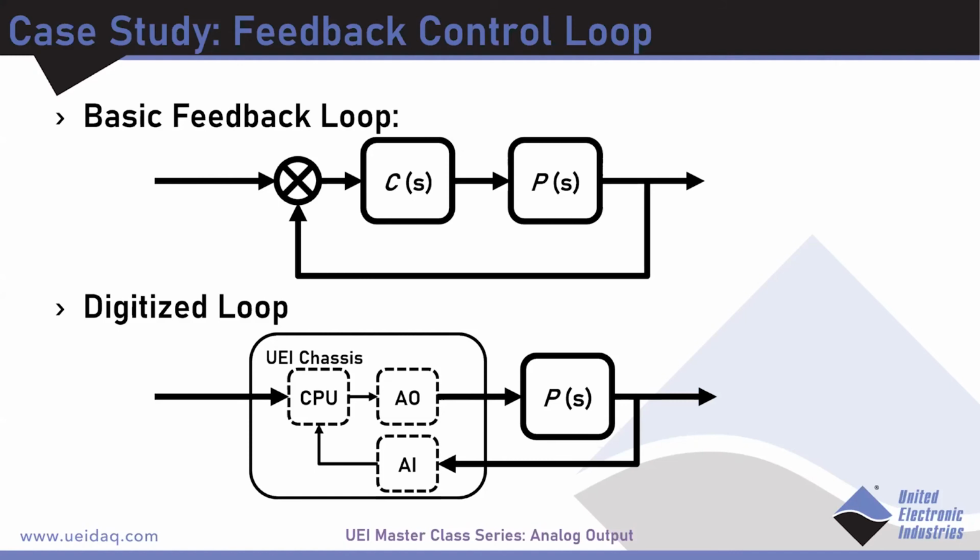Oh, looks like there's a follow-up to that one. Can I use an amplifier for current or voltage with your boards? And the answer to that is yes, absolutely. I believe we actually supply a current buffer board as a starting point to show that you can amplify the output of an AO 308, I believe, or the output of any board. Our amplifier board is specifically designed for the 308, but it worked with the 364 as well. The point there being, you can use pretty much any amplifier depending on the power characteristics you need for your device.